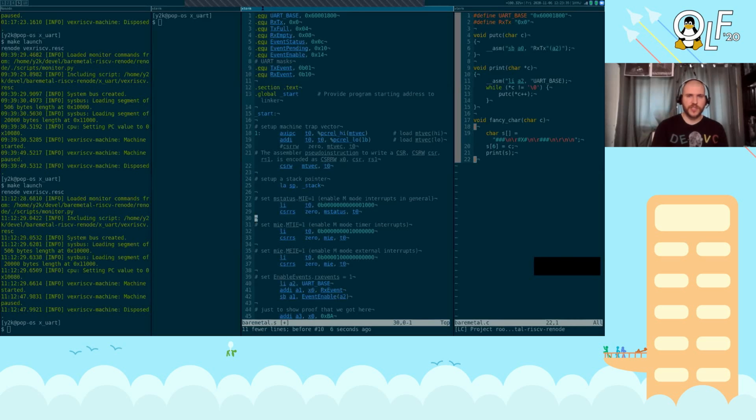Here is the memory location that we're going to be accessing. So this UART base, UART is universal asynchronous... I'm not sure, but it's a serial connection, or it can be put over serial. Each of these are the offsets for receive and transmit, and then different signals. If the buffer gets full, or if there's nothing to read, these signals are turned on. Writing ones and zeros to each of these registers, which are offset in memory from this base, allows it to read and write to that piece of hardware. So it's memory mapped I/O, and it's going to be a serial port.